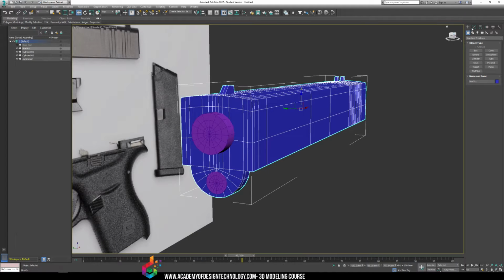So what I'm going to do is I'm going to have this part of the gun. I'm going to use this. I'm going to give it a compound object, create geometry compound objects, a Boolean tool. What a Boolean tool does is allows you to cut an object using another object. Meaning if I click Boolean while I have the gun top part in my grasp right now selected, I click Boolean, that's the main object that appears in my scene, which is called box 001.